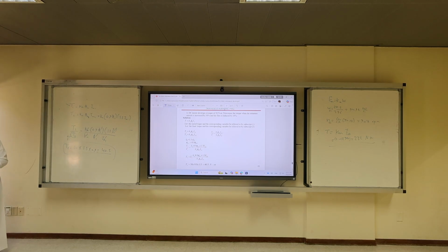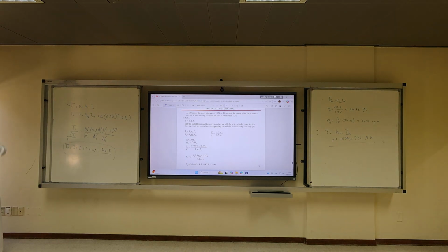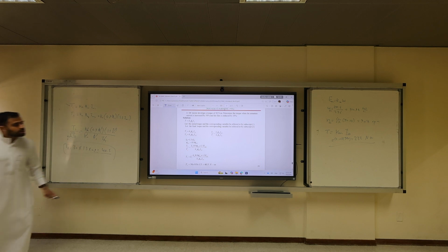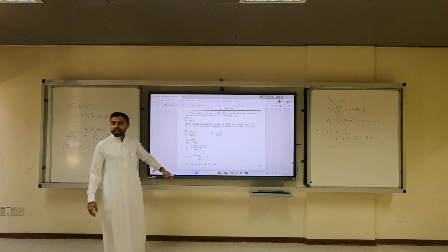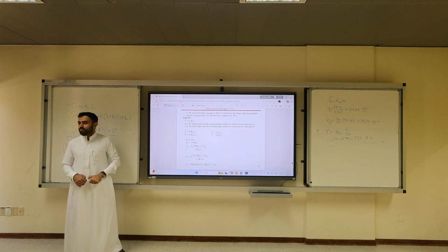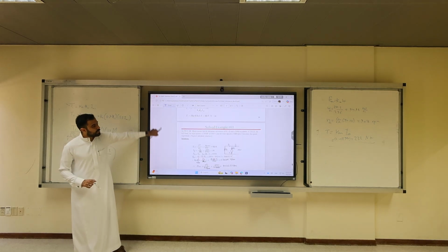For the same machine, if you increase the armature current, it will increase the torque. If you decrease the flux, it will decrease the torque, because the equation here is clear. They have the same motor, and there is a relationship between theta M1 and theta M2 and Ia2 and Ia1. Is this example clear? Any question? Let's go to example number 3.